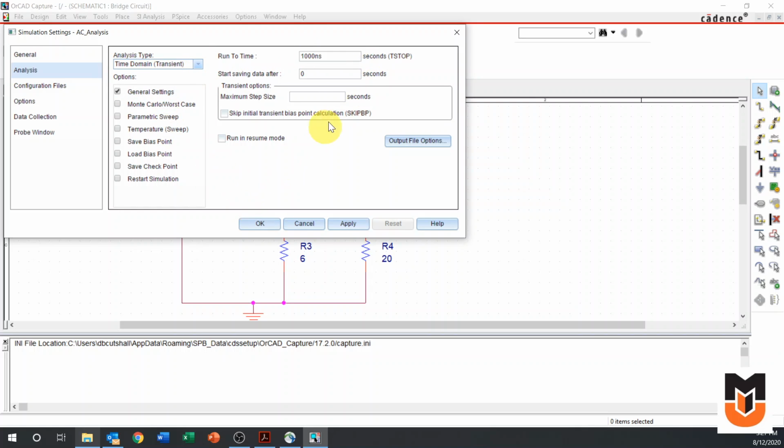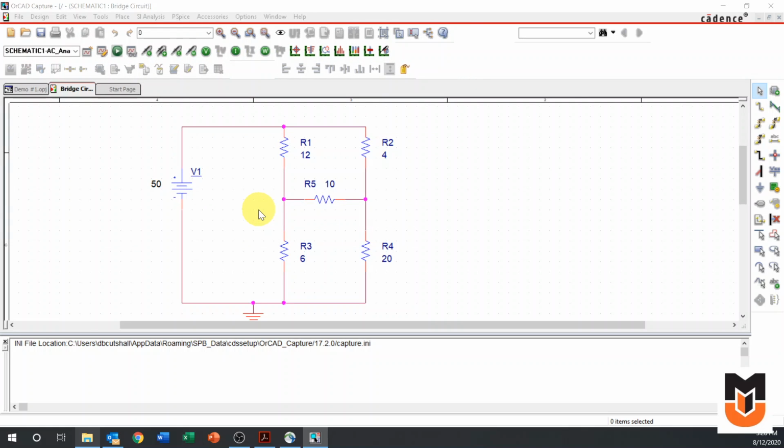We're going to see in some later videos exactly what we need to set up here, but for now we're just going to have a placeholder simulation profile. So now that we have two, we can see from this drop-down menu, we can select between all the profiles we've created. That means we can do multiple different types of simulations on the same circuit. In this case, we want to stick with our DC analysis, so I'm going to select that one.